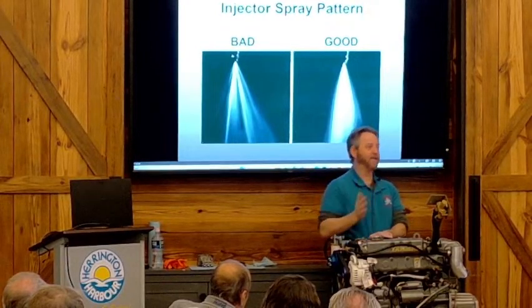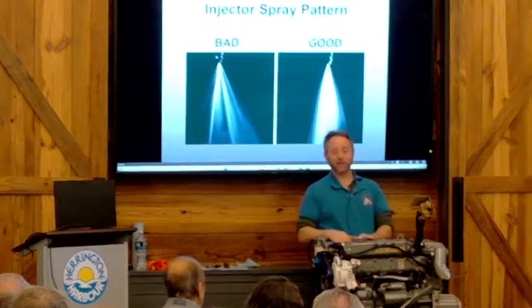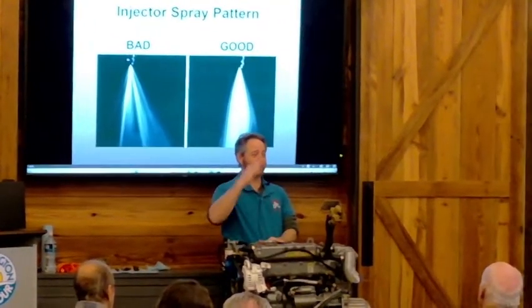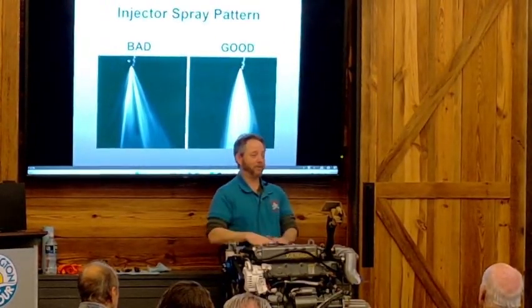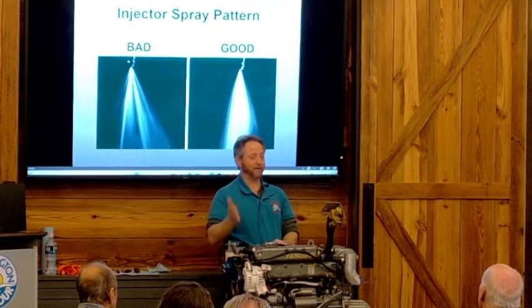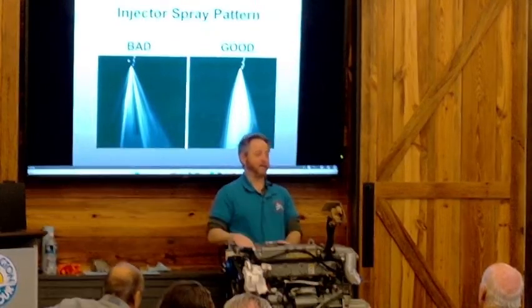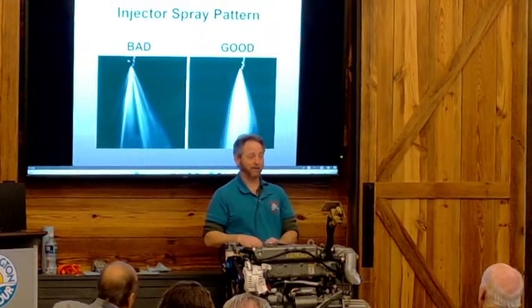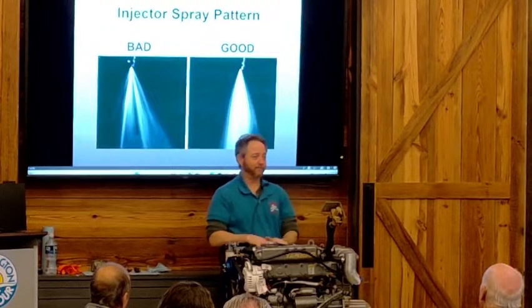But just because it doesn't change when you do a wet test doesn't mean it's not a bottom end problem. I did have one engine fool me badly. Did a compression test, did a wet test, it didn't come up, so I pulled the cylinder head off, had the head rebuilt, put it all back together, started it back up, and that cylinder still misfired. So I pulled the engine out, pulled the pistons out, and on the front cylinder the connecting rod was bent.